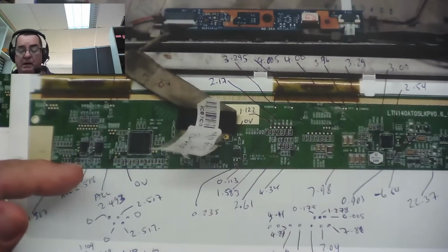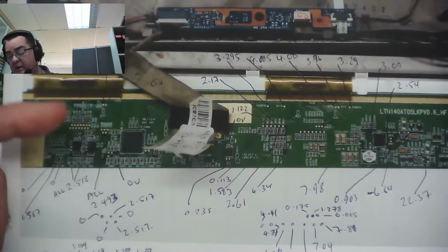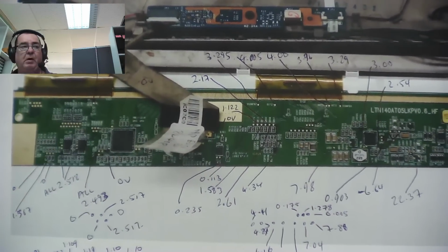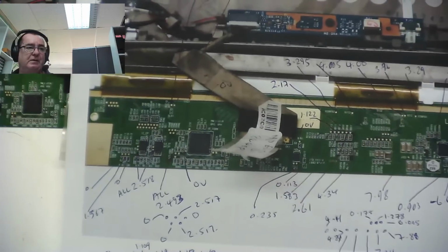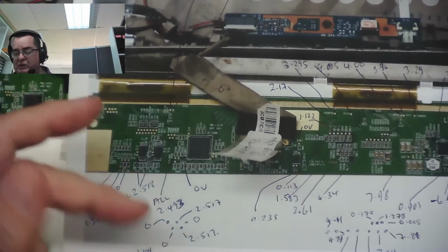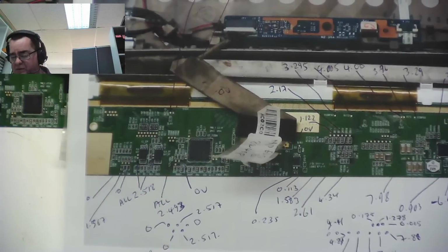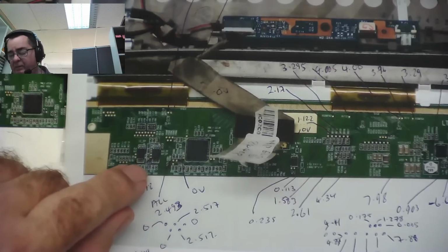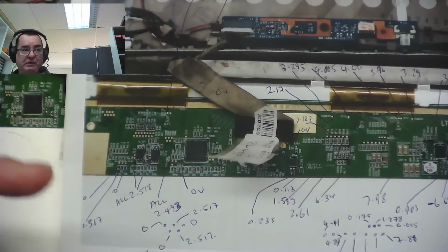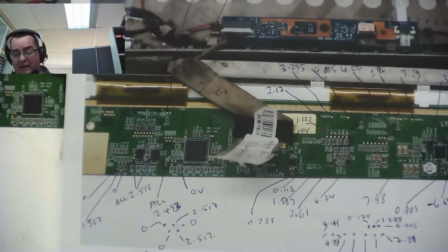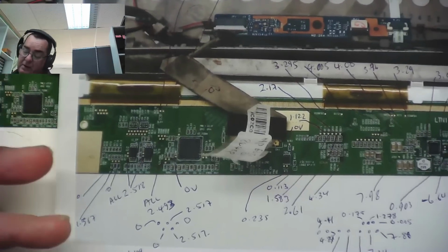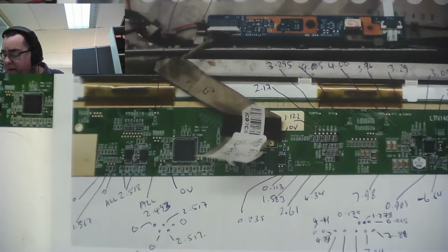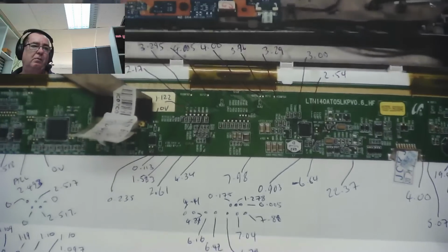If you watch the last bit of the video, we took the EPROM off, and somebody sent me a file with the correct contents. Even though I'd swapped the EPROM, we thought, okay, let's just check them. I checked both of this EPROM, 402WP, which is telling me is the right one. I read the contents, compared them with this file, and they were the same. So we're still back to this thing: what's wrong with it?